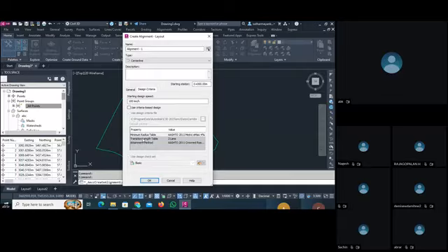Civil 3D uses the standards like IRC, AASHTO, RTA, and for Kenya, KeNHA. So these are different countries' codes. Civil 3D uses these codes and designs the road correctly from the starting point. If you select the criteria based design, for example, if you select the design speed of 80 kilometers, Civil 3D will automatically suggest proper curve radius, super elevation, all the things as per this design speed. So criteria based design is designing with rules. You have to understand this first concept.